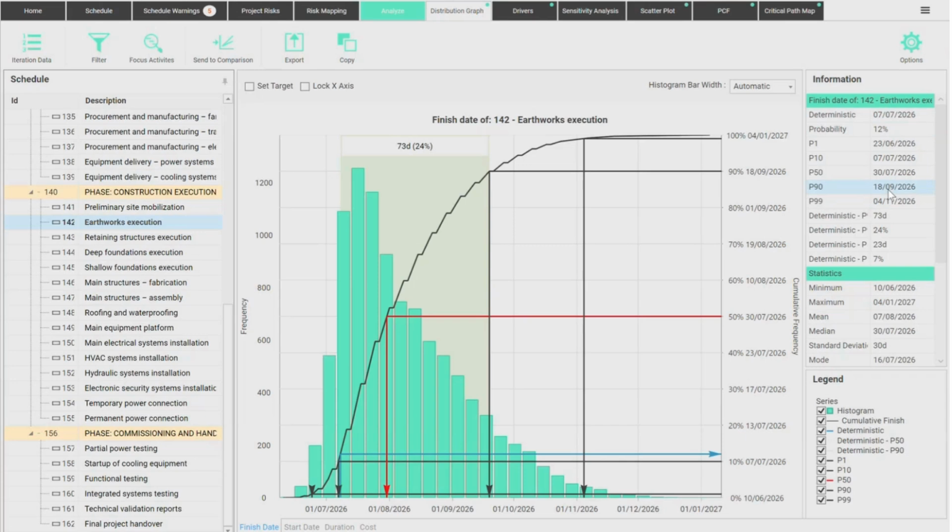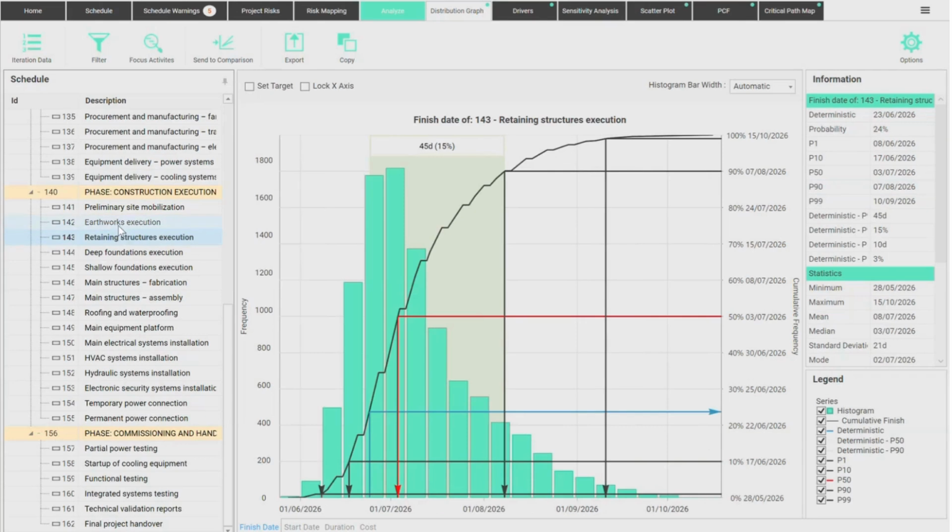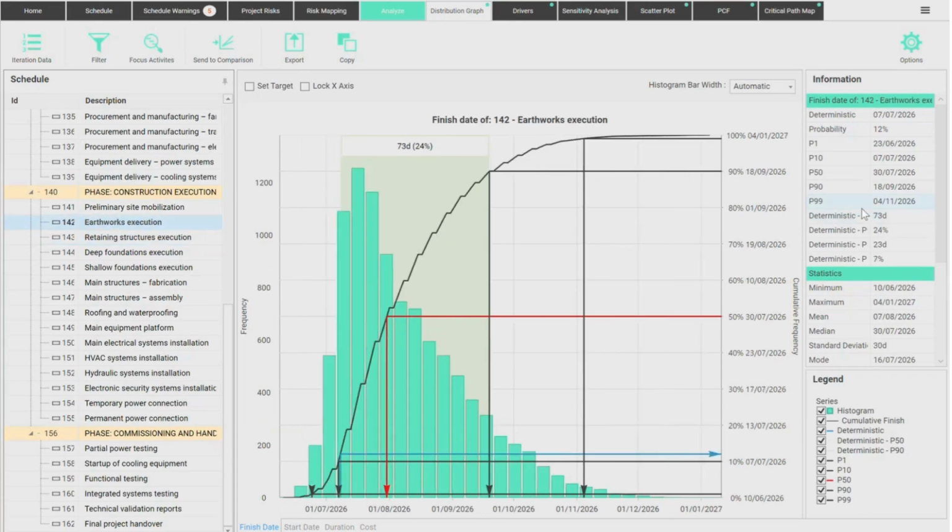Actually, you could come back to your deterministic model and assign whatever task comes after earthworks. Assign this task a don't-start-before, put a constraint on the start date of the next task to make sure that you don't start it earlier, to make sure that you don't spend money or resources before you need them. That typical trade-off of cost versus schedule that we face when managing projects, right? So from the risk analysis result, you can assign better contingencies, you can control better, and you can actually plan better, change your base case to account for the risks or to react to the risks, okay?